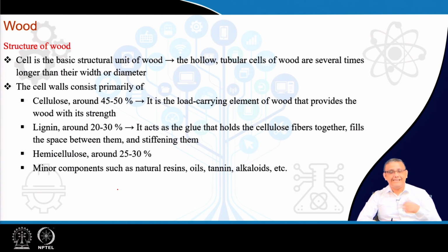Among that, cellulose, which is around half of the wood's constituent, is the main load-bearing element of the wood, and it also provides the wood with its typical strength and stiffness, which we actually look for in structural applications. Then we have the lignin, which is around 20 to 30%, and this lignin acts as the glue that holds the cellulose fibers together.